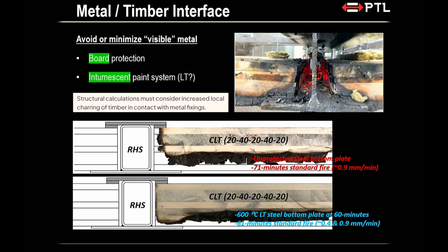What you're saying is, what if you have a few timber blocking here, hard up against the steel, and then that part wouldn't intumesce? Yeah, but the timber helps to protect it as well. Yes, exactly, you're overcladding it. Like the timber might fall off, and your paint could still intumesce then, potentially. But these are the sort of grey areas that nobody...